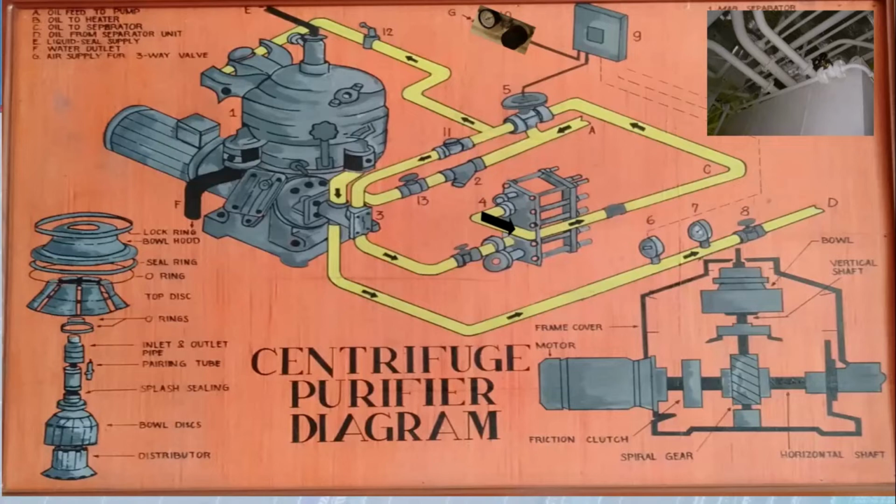The settling tank should be 85 to 95 degrees while the fuel oil service tank is around 95 to 100 degrees, maintaining temperature, while the check valve opens and the fuel oil flows for the fuel oil circulation system.